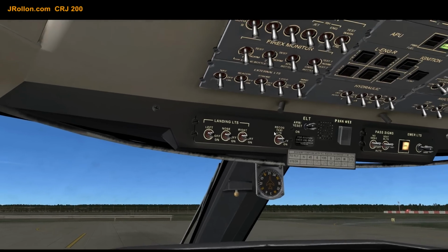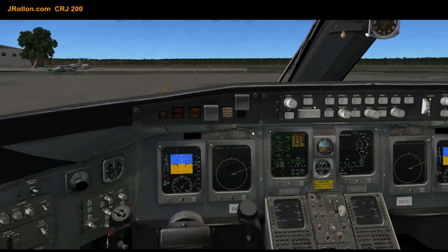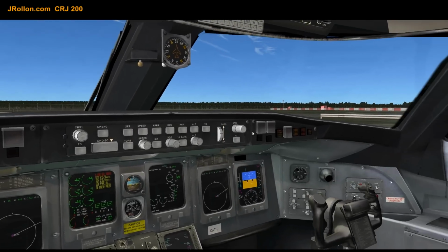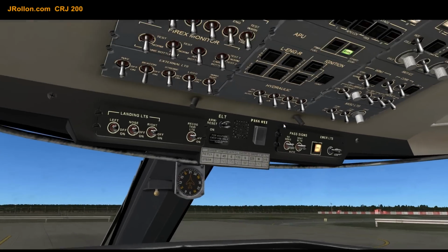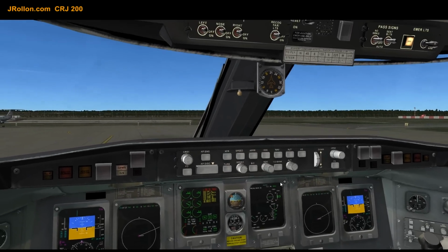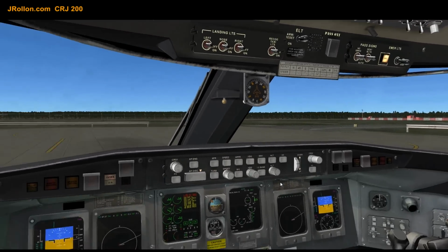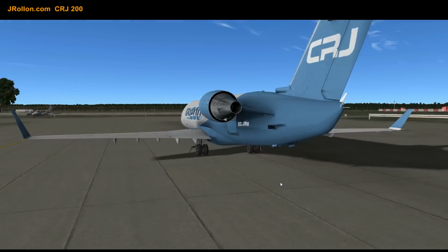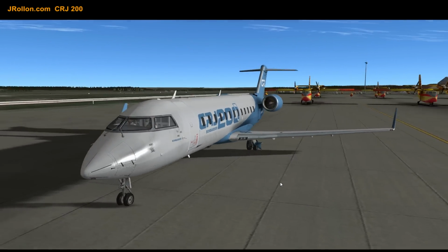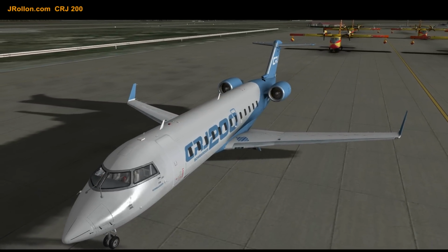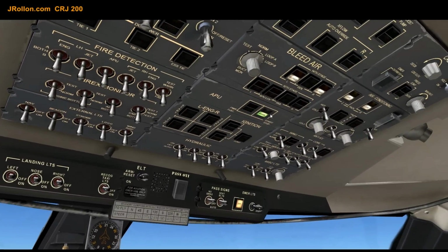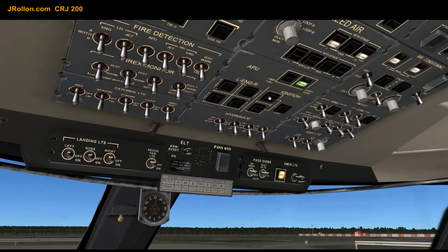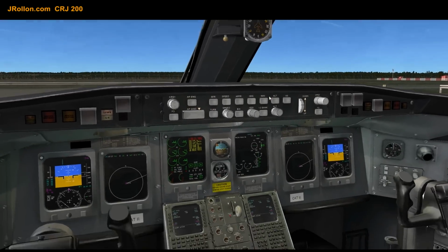So they give us permission to start the engines, so we switch off the beacon, the light, the red one, the collision one. We have to first of all give air to the engines, because the engine blades, if you go outside, are very big, so they cannot rotate at the beginning. So the thing to do is use the air coming from the little engine, that is the APU, to move those bigger blades.